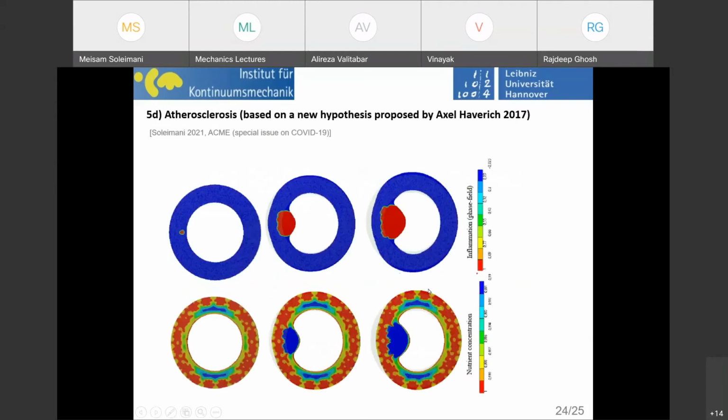I mean, for example, in plasticity, everything has been well established. We know that in plasticity, it's taken from the maximum dissipation theory. So it means that the evolution of a plastic deformation is defined in such a way that the dissipation is maximized, right? It's already there, it's built in.